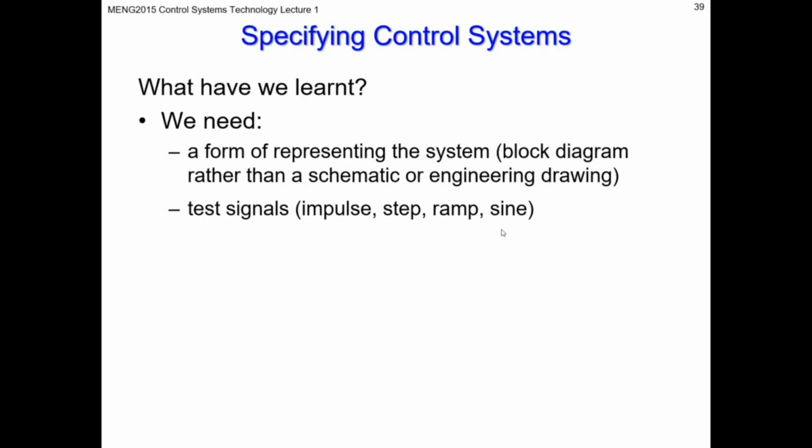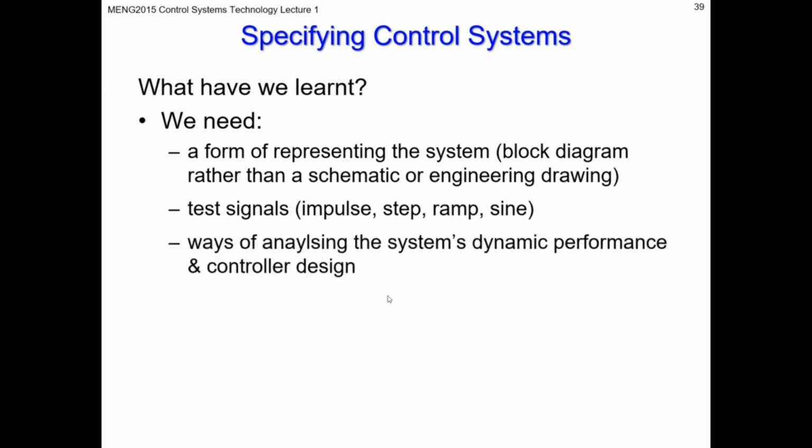Sinusoidal inputs, we use a lot when we're doing frequency analysis, because when you apply a sinusoidal input, you can see the frequency response of a system, including its control system, and we can learn a lot about how a system behaves by looking at its frequency response. So we can apply a known frequency of known magnitude at the input. If we measure the output frequency and magnitude as the system is oscillating, then we can learn about the dynamics of the system by comparing that input and output.